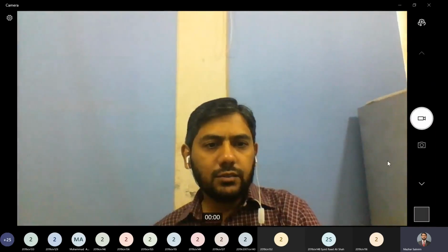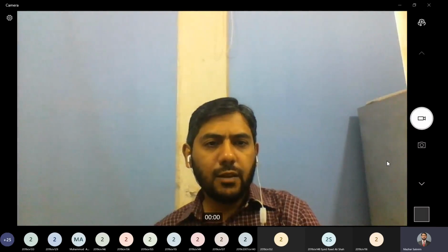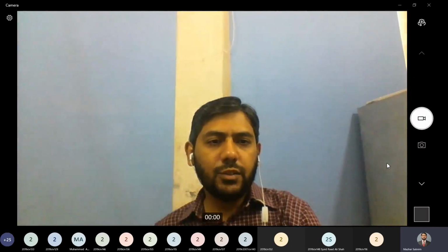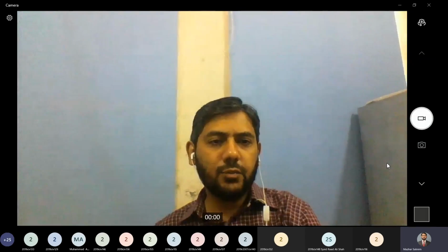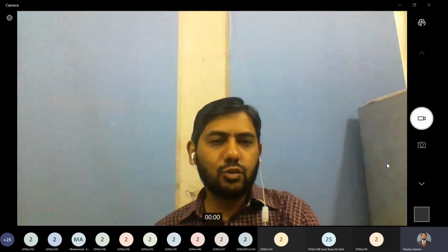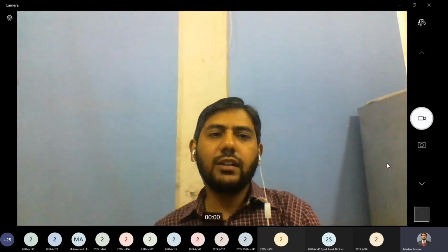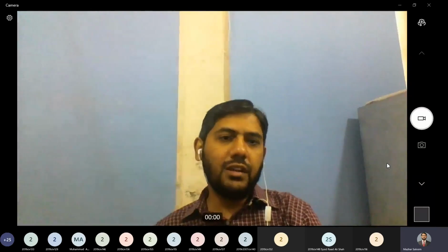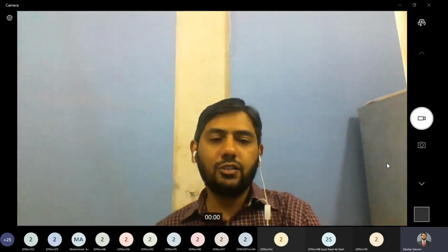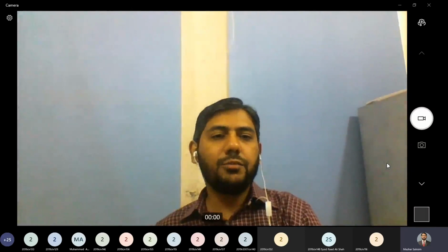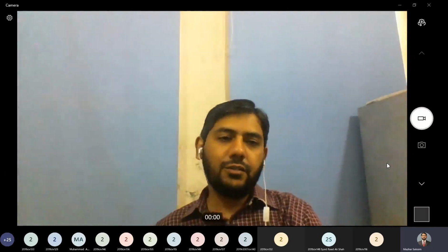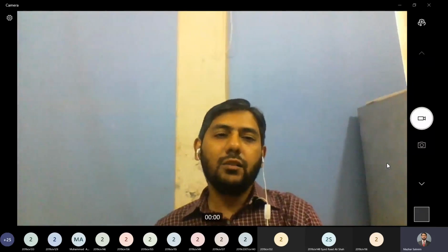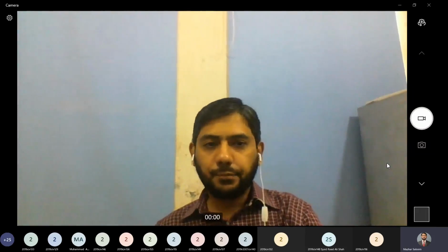Okay, we have a couple of questions here. By the deflection of beam, do we mean the vertical distance between undeflected and deflected position of the beam, or any other concept? So I think we already answered this question, that if the beam is horizontal and it is subjected to vertical loading, then yes, we mean the vertical distance between undeformed shape of beam and deformed shape of beam. But the deflection may or may not be vertical in all the cases. It may be horizontal, or even it may be in some inclined plane.